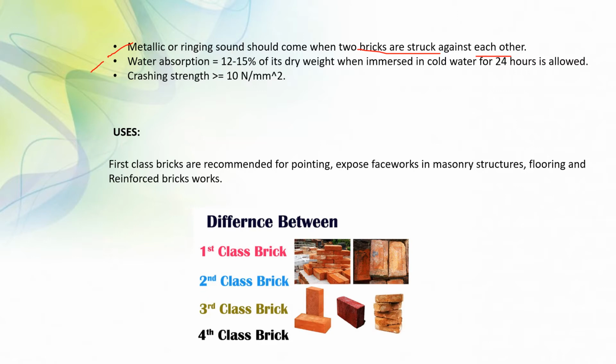Water absorption of 12 to 15% of dry weight when immersed in cold water for 24 hours is allowed. Crushing strength should be greater than or equal to 10 Newton per millimeter square. Next, uses of bricks.